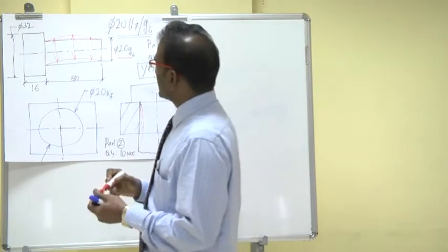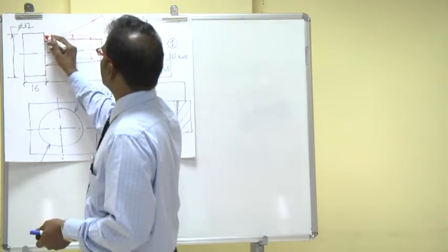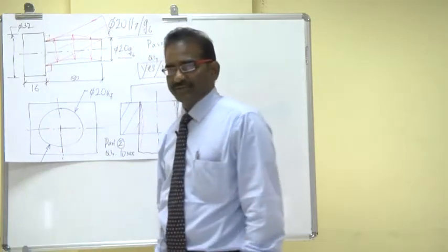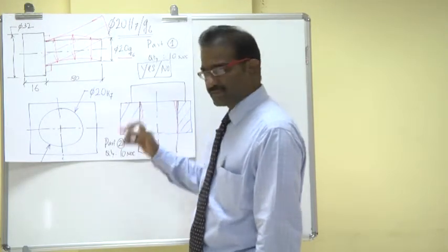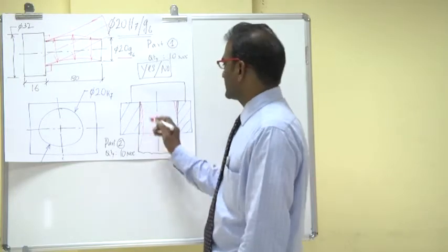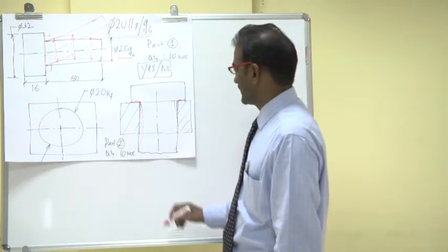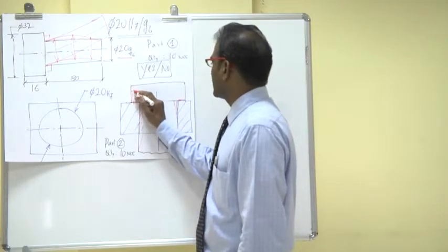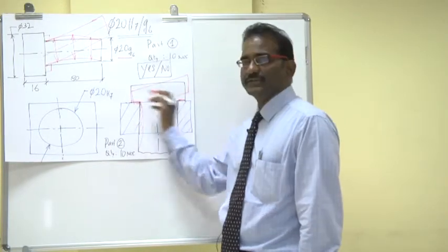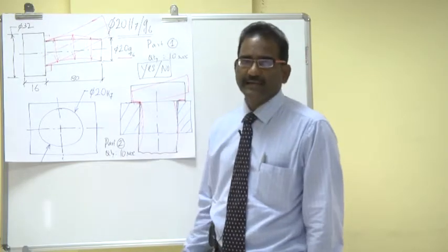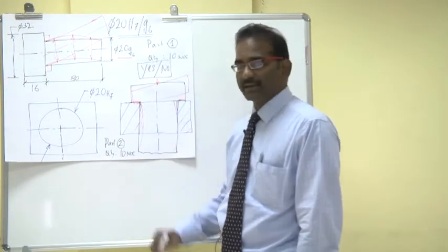Similarly, there could be yet another situation where the dia 20 area is not normal to the face. The shaft is bent at an angle of say 1 degree or 2 degree, whatever it is. In this case, what could happen in the assembly is, again, I will not be able to get a good amount of seating area once the shaft enters inside the hole. In other words, I will have the shaft seated perhaps at 5 degree, and instead of having a surface contact, I will realize only a line contact or point contact, which will not answer again my design requirements and load bearing characteristics, etc.